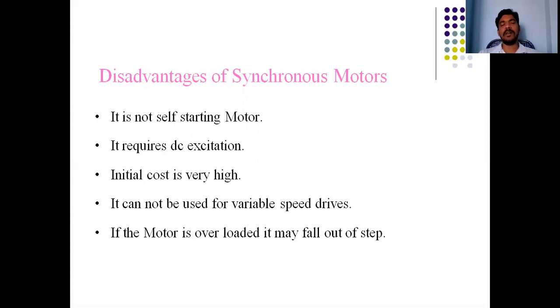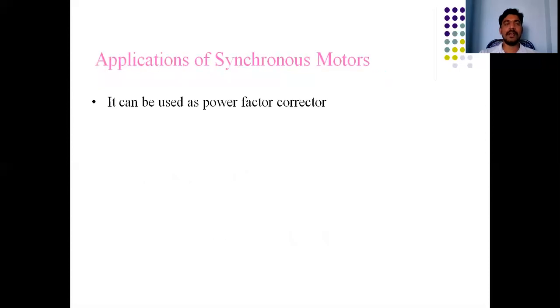After that point, if we increase the load, the motor comes out of synchronism and it will stop. This motor cannot work on overload. It has a tendency to hunt. Hunting is also present in the induction motor, and in the synchronous motor.